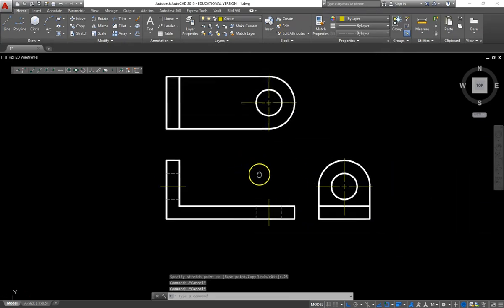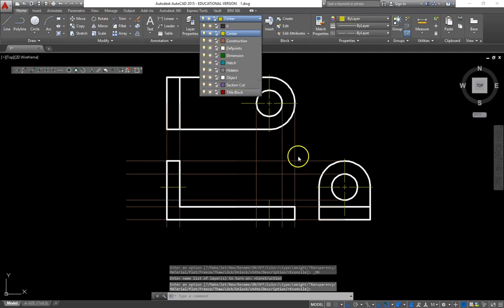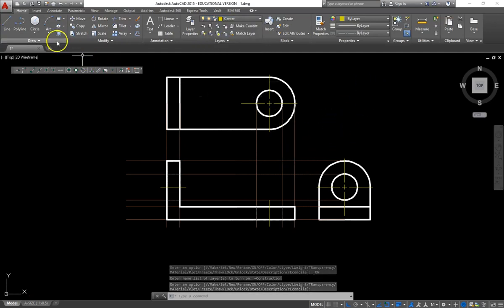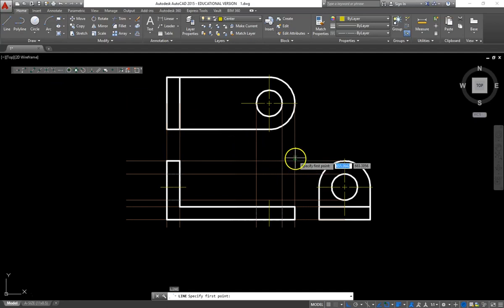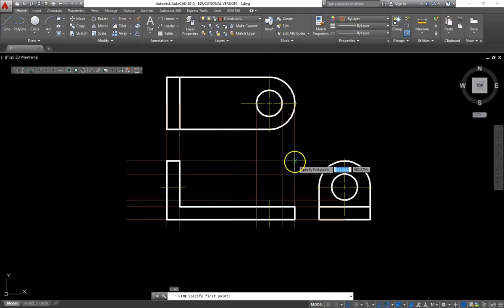All right. Now we are almost complete because we have projected our lines across and down. However, this hidden set also should appear here, and this hidden set should also appear here. Now there's two ways to do this. The correct way is to project across from your miter line. So your miter line is a 45-degree line, as we learned in our last video, from the upper right-hand corner of the front view's location. Angle 45.